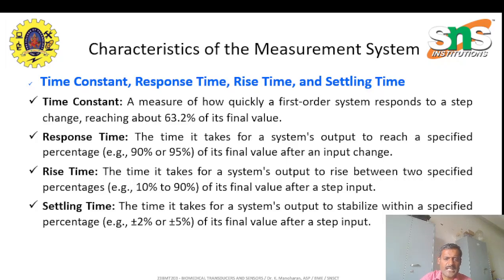Next will be rise time. The meaning is in the name, rising time. It is the time the system output takes to rise between two specified values, from 10% to 90% of its final output for that input. This is called the rise time.